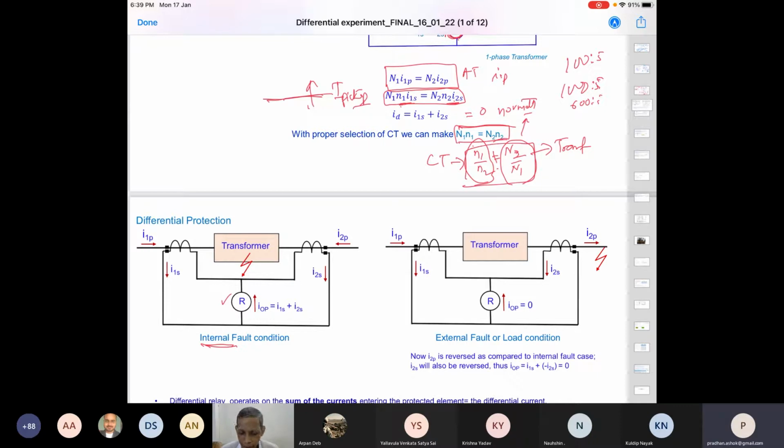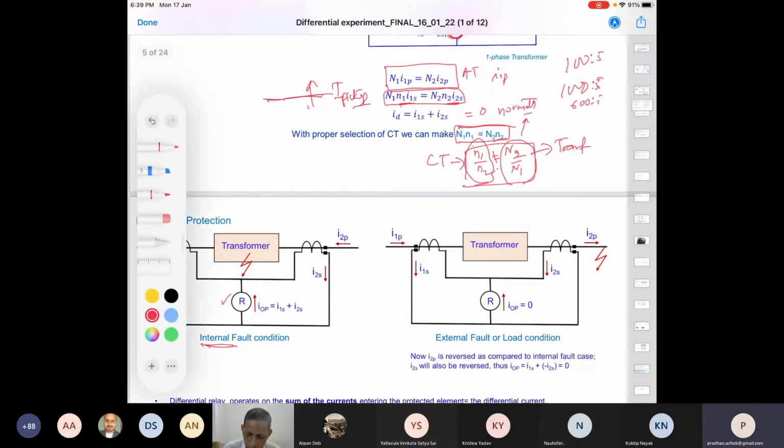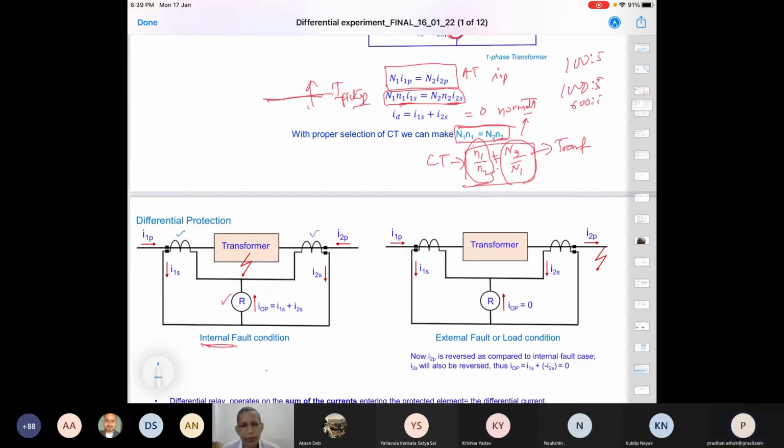Now the relay is taking judgment through what? Getting the signal from the CT. So who has the CT? This is one CT, this is another CT. So the zone of protection, or the section for which this relay is taking care of protection, and the associated breaker to which it will trip, is nothing but from this to this. So the transformer and the allied connections from here to here are taken care of by this relay and the protection arrangement.